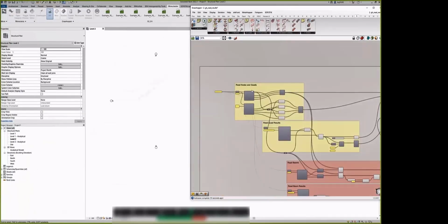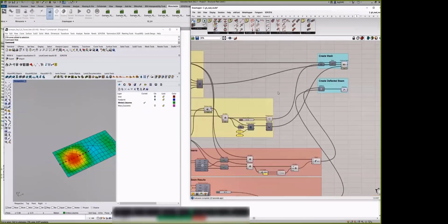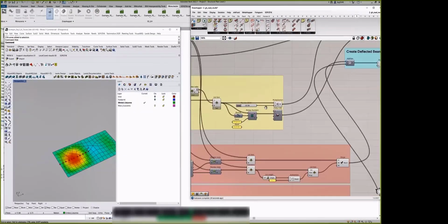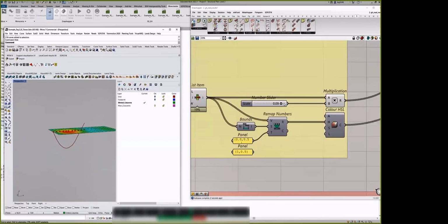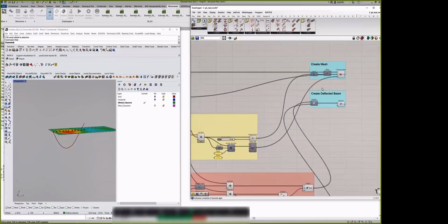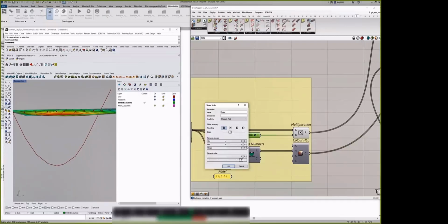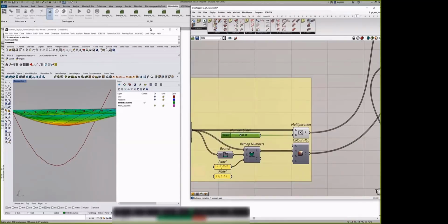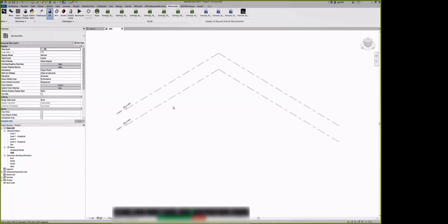And this case is again previously mentioned. You have that analyzed from calculation software, and then you can stream those output results from your structural report, and you can stream the coordinates and different numeric attributes as variables. And if you have generated an Excel sheet, you can also read it in Grasshopper. This is very typical Grasshopper data interpolation.